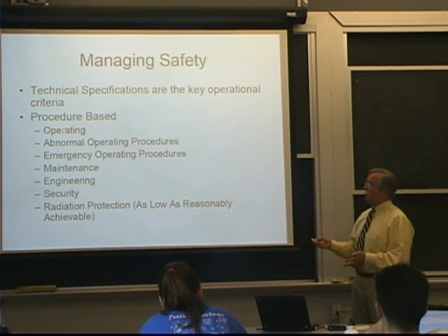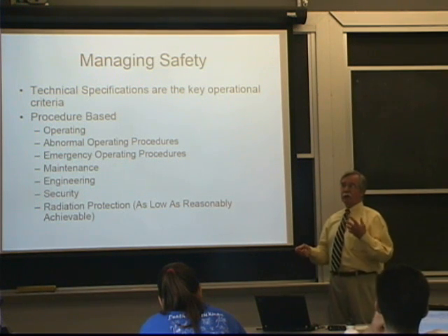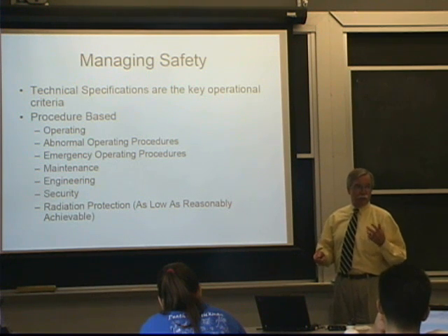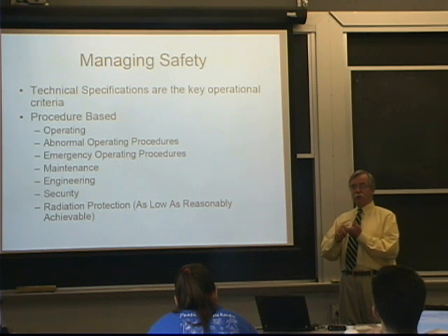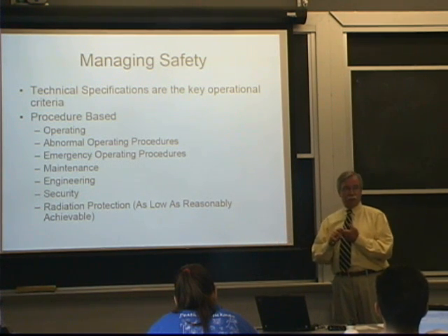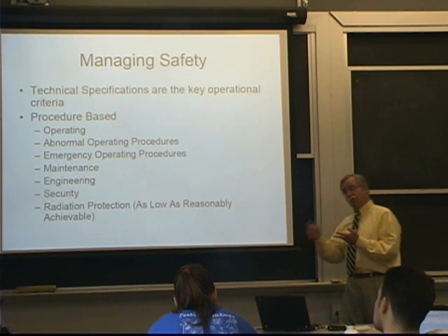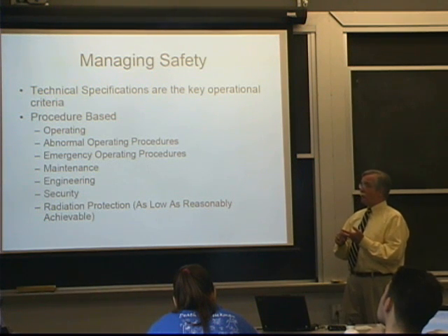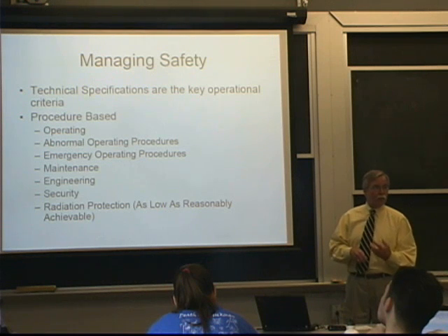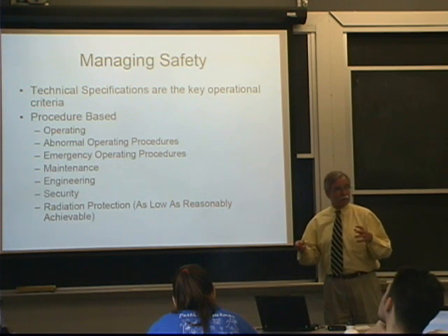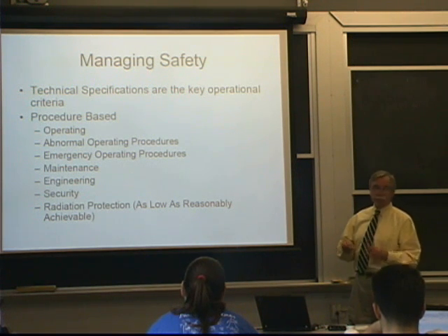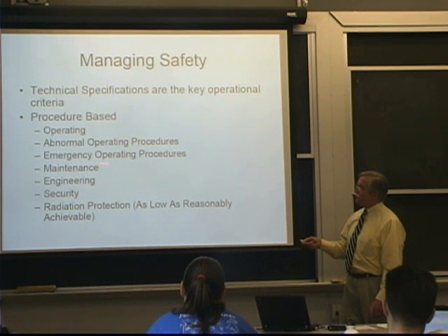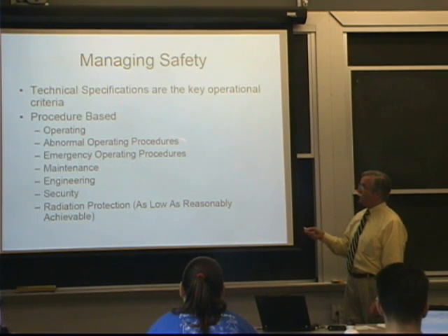And many of these operating and abnormal operating procedures, and certainly abnormal emergency procedures, are symptom-based. They used to have procedures that said, if pump number 1 breaks, you do this particular step. If pump number 2 breaks, you do this particular step. However, they found that pumps don't always break in that order, or things don't always happen in the way people have postulated. So they have symptom-oriented operating procedures, which most of the new plants and old plants have converted to,